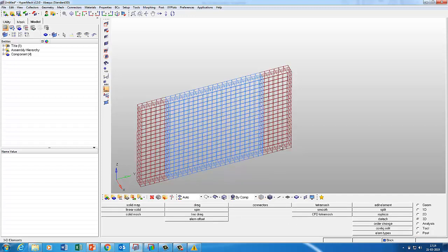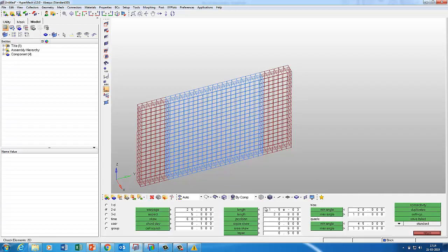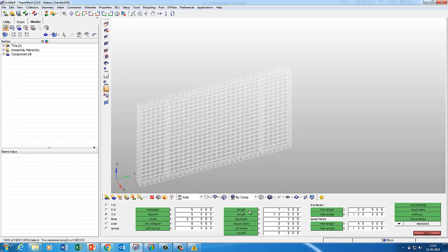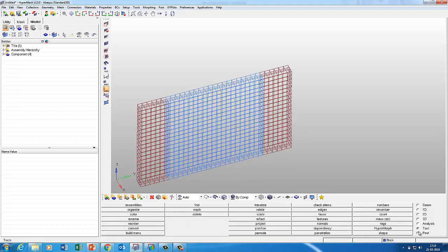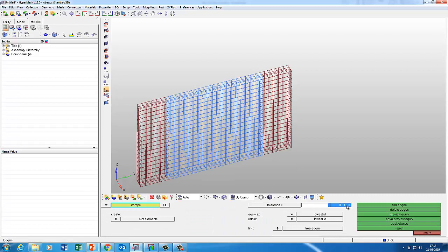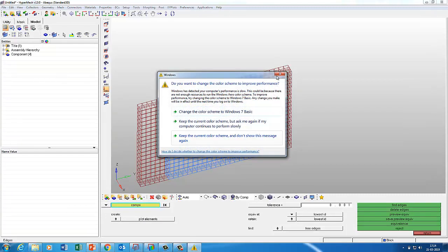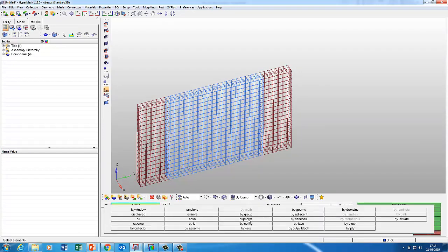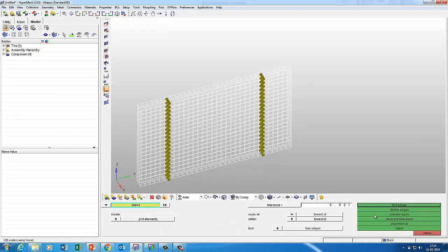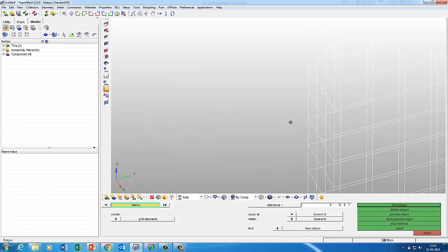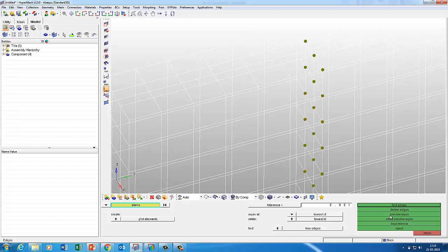So first we'll just merge it. For merging, you go to tool, I go to check element, you say 3D, and first check what the length is. The length is like 0.003, but if we have to merge it, we'll use Shift F3 and merge with less than the length size. So 0.01, that's what we'll put, and then I'll say element display, preview equivalence. So you see this many nodes are not equivalent. The first node was equivalenced, but the others were not. So you say equivalence, so they are merged now.